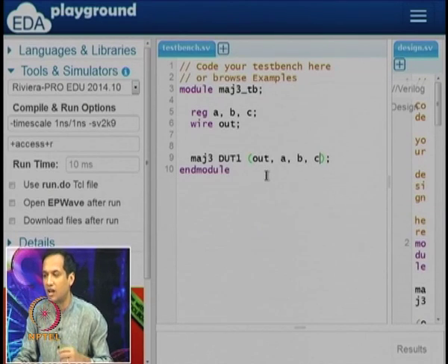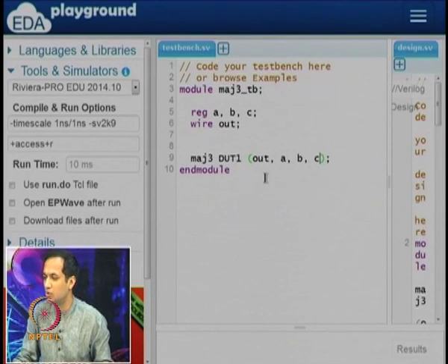By accident you do not want to connect an output to a voltage supply and an input to be connected to the oscilloscope and so on. So what I have done is I have declared local variables here which are supposed to be connecting to VDD or ground and whatnot, and I have maintained the order in which the design is expecting the inputs and outputs.